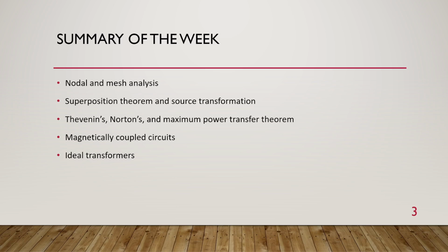Remember that in the case of DC circuits, excited using a DC voltage source or current source, you actually didn't have any capacitor or inductor. Or even if you had, it didn't matter, because in the steady state they are as good as not present: the capacitor simply becomes open and the inductor simply becomes short.